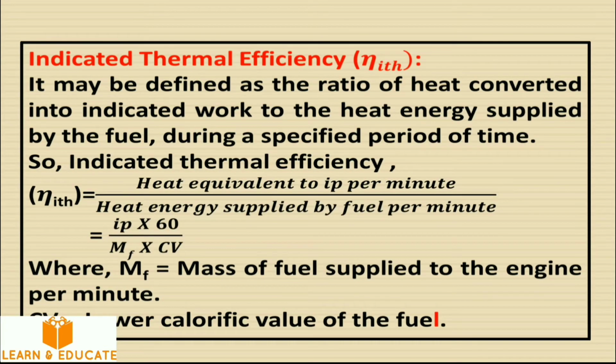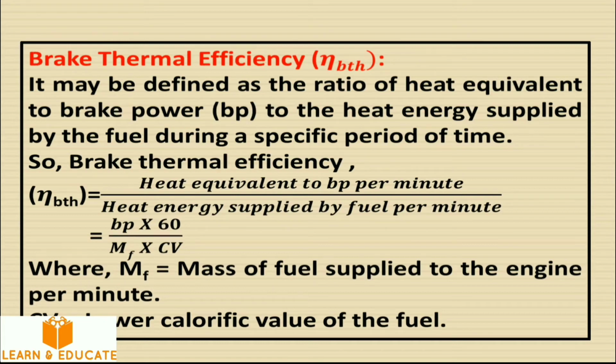Then indicated thermal efficiency is defined as the ratio of heat converted into indicated work to the heat energy supplied. So out of the total heat energy supplied in the form of fuel, how much is converted to indicated power within the engine cylinder? That is indicated thermal efficiency.